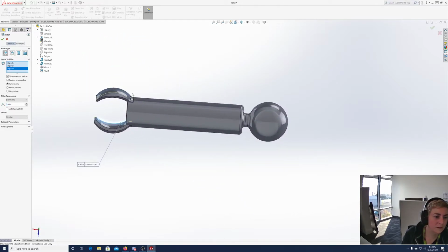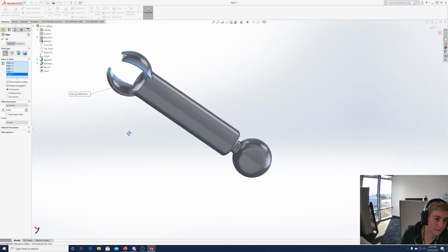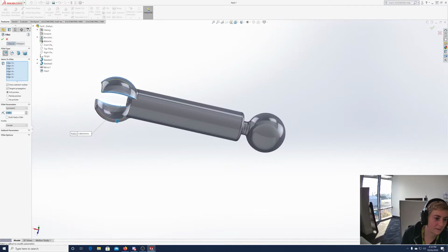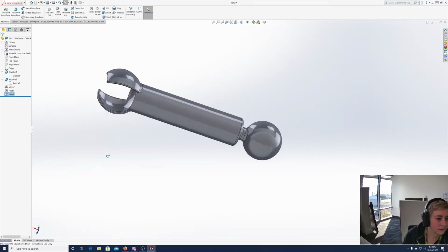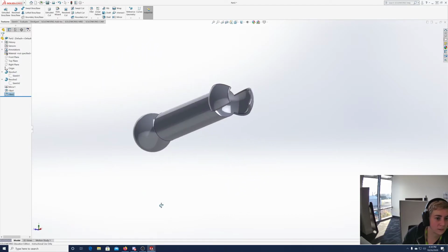That's probably because of the... Did you put in the radius as 0.08? Okay. No worries, that'll do it. Yeah, so it should be 0.08 and then... Cool. And then the second one is going to be 0.015. And you'll see those little edges there all show up.